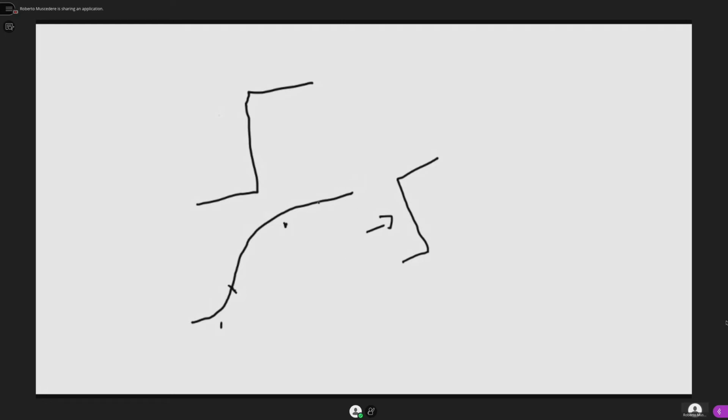Now, if the circuit isn't being loaded down, it's going to transition faster. So a faster transitioning circuit going into a buffer is going to work better if you have the things behind the buffer, assuming it's a larger buffer, where it can handle it. The only downside to this is that I need a buffer and it might have to be larger, so the circuit gets bigger. So this is why we want to avoid these types of situations.